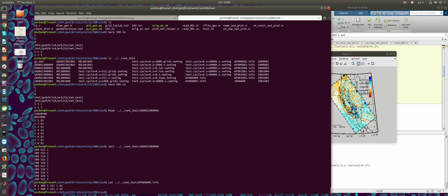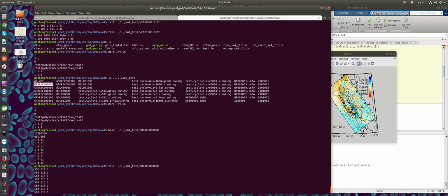So once I have created those recording grid files using skg.py, I can run SW4 with the first line of inv.in set to 1. And then SW4 is going to create those model files, and then stop. Right? It's not going to do wave propagation simulation. If I want SW4 to actually do wave propagation simulation, I have to increase this number to 2.